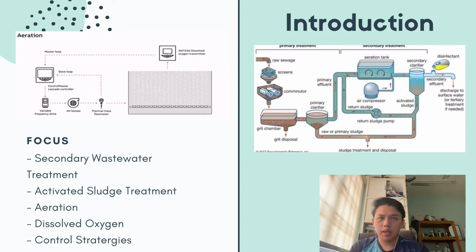In wastewater treatment, when the concentration of dissolved oxygen is excessively low, it will affect the activity of microorganisms because the environment has become anaerobic. The microorganisms are not able to react with sludge. This requires the plant to conduct a high-cost and time-consuming biomass replacement process, which is not economy friendly.